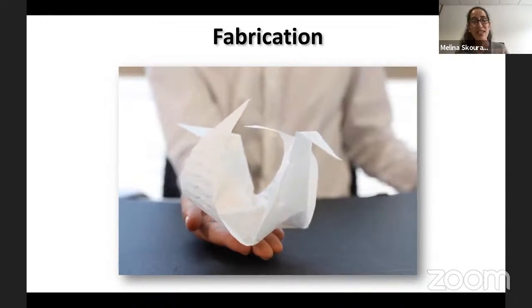One interesting thing to note is that when the heat sealing head gets in contact with the fabric, it applies forces on it. And this will create a small depression on the top layer of the structure. And this asymmetry will make the hinge bend in the preferred direction.